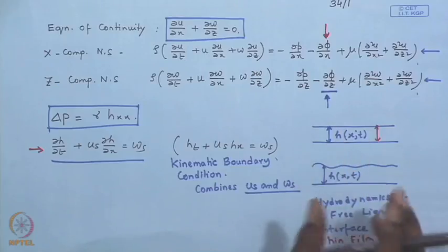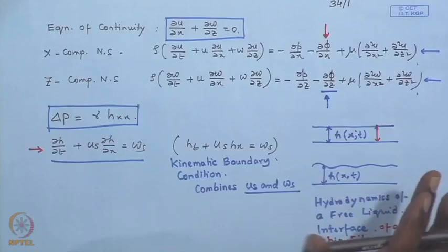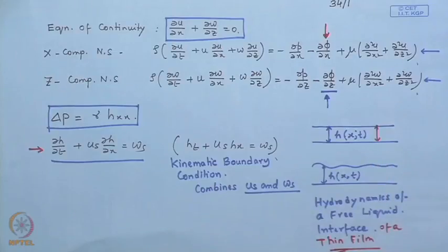Now, the expression of phi can have terms which represent only the van der Waals interaction, or additional terms that take care of additional interactions, let us say acid base, polar or steric interactions. You can use this form of Navier-Stokes equation for all your fluid dynamics derivations so far, because do not forget that phi will be a function of h, the film thickness.